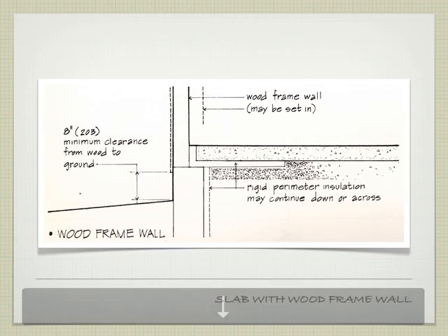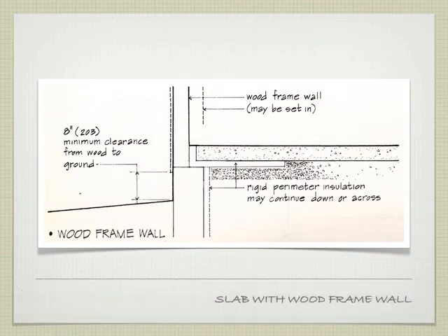I'm not asking you to draw each one. I picked the generic one. But I at least want to talk through some other things that do happen in a slab on grade, and we will cover slab on grade in more depth in a couple lectures. So in this particular example here, we have our slab, but we have a piece of rigid insulation that's separating the slab and the interior from the exterior, which is part of what we're doing for environmental reasons, heating and cooling of the building, that sort of thing.